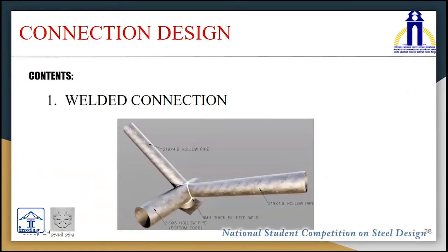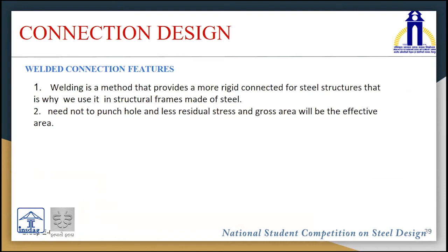Next, we have the design of connection. Our truss is mainly having welded connections. Welded connections are rigid and lightweight. No hole is required for the fabrication of welding. Thus, the gross area of the sections will be acting as effective area.